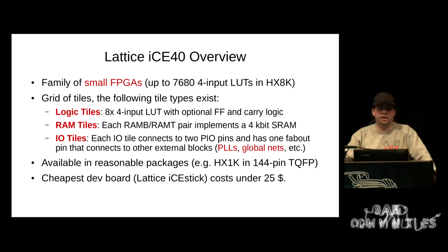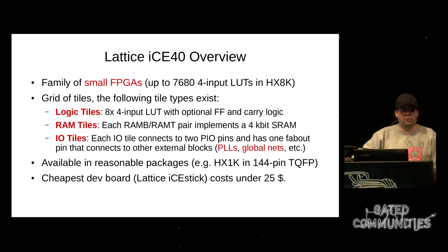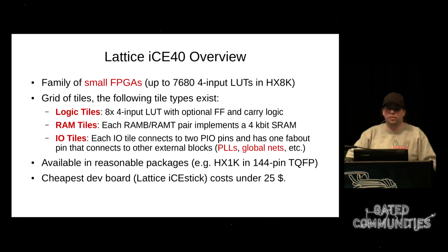And of course, there are I/O tiles on the edges of this grid that connect to the programmable I/O pins, but also provide the infrastructure necessary to connect the FPGA logic with other resources on the chip, like PLLs and global nets.